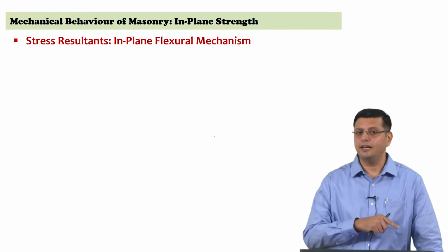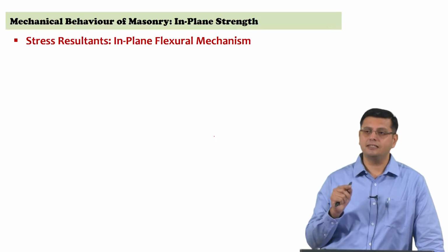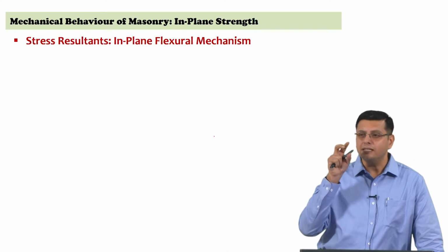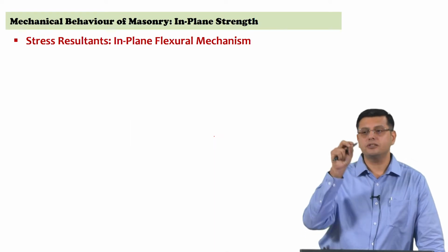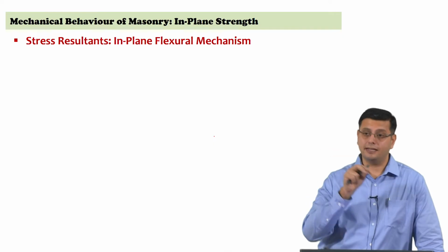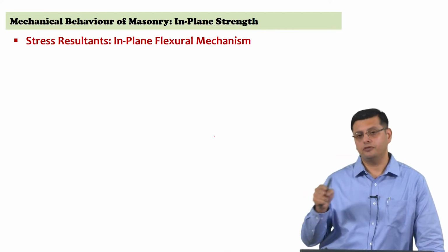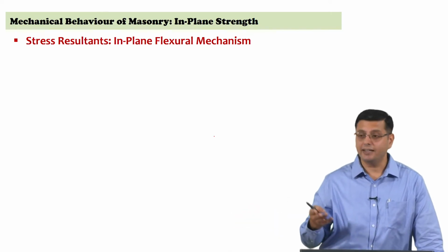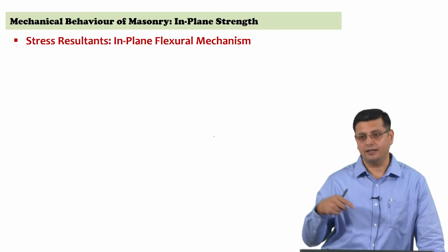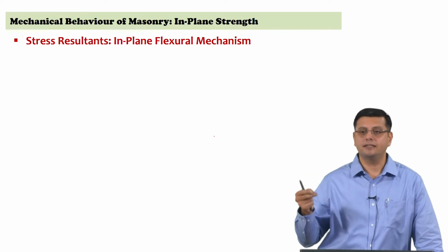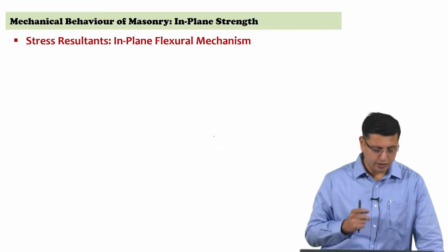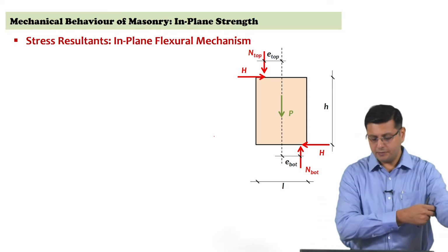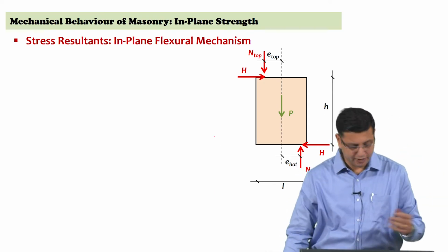Earlier we had looked at in the manual criterion, the second criterion was when the tensile strength of the unit was reached, but now we are not going to be examining it in terms of the unit or the mortar, we are going to be looking at tensile strength of masonry. So, instead of FBT, we will start looking at the tensile strength of masonry, and that is where the diagonal tension, diagonal compression test that we looked at earlier as an estimate of the tensile strength of masonry starts becoming useful.